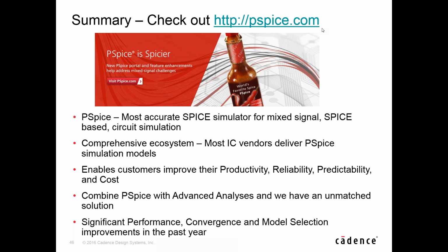That's a great question. Yes, they can. I probably should have covered that in the demonstration. After you run the optimizer and you get those ideal component values, like a resistor of 733.5 ohms, you can then switch it over, and we have a discrete engine in the optimizer that can take the ideal value and find the closest real discrete component value that you have available in your library to use as the final result.